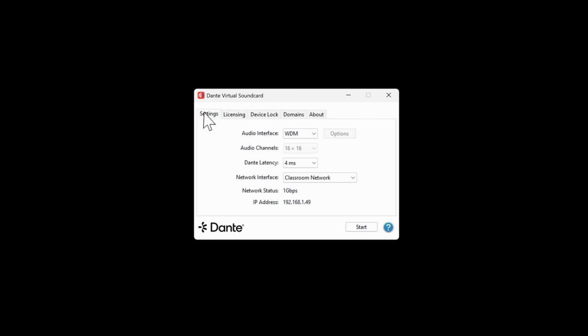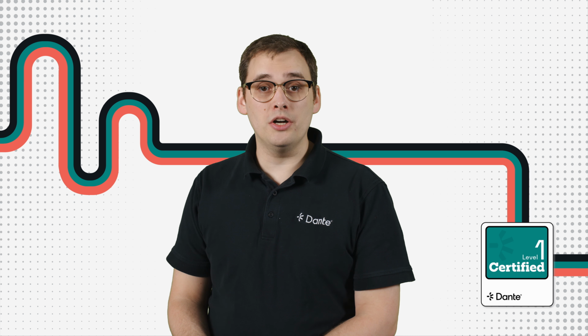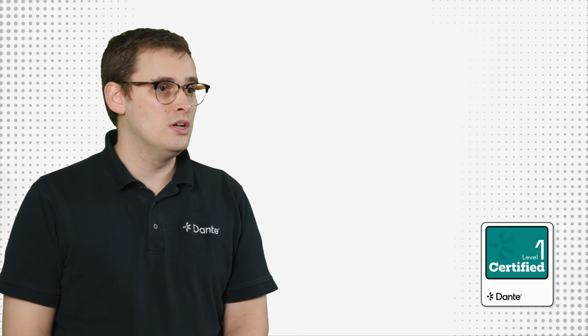We'll start by opening the Windows version of Dante Virtual Soundcard. Once opened, we'll see the Settings tab. In the first option, we'll choose the audio interface, either AVIO or WDM. In WDM mode, Dante Virtual Soundcard supports audio applications that use WDM audio, such as iTunes and Windows Media Player. In AVIO mode, Dante Virtual Soundcard supports audio applications that use AVIO audio, such as Steinberg Cubase and Nuendo, Pro Tools, Ableton Live, and many others.